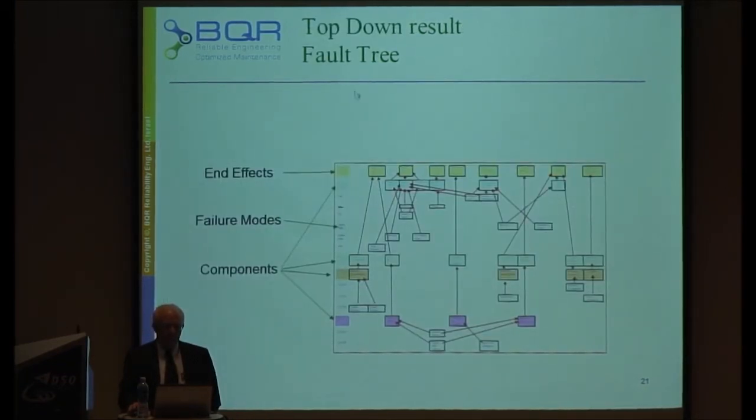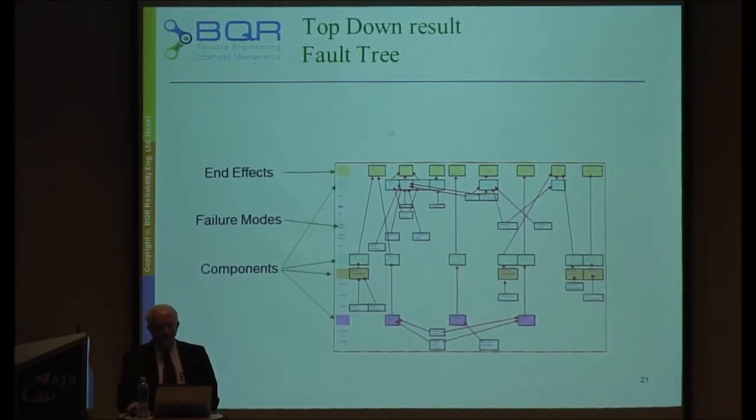You can see that also as a fault tree. So we have end effects, and we see the components contributing. Now we can inverse it and, having those end effects, see what can cause those end effects. So there is a connection between FMECA and the fault tree. So the FMECA is a bottom to top analysis from components to product symptoms, and then we have the symptoms down, what are the causes. This is the fault tree. So this is a different view of the failure propagation.